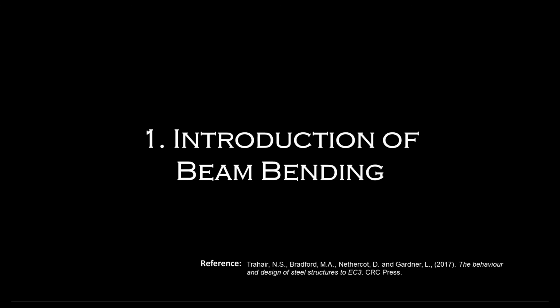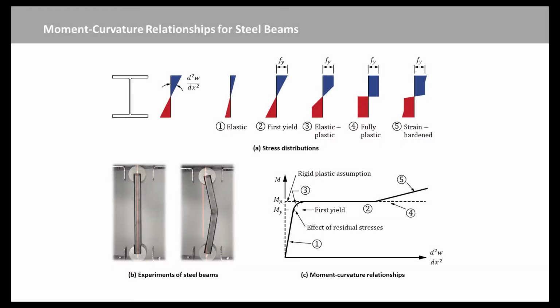Beams are structural members which transfer the transverse loads they carry to the supports by bending and shear actions. Beams generally develop higher stresses than axially loaded members with similar loads, while the bending deflections are much higher. These bending deflections of a beam are often, therefore, a primary design consideration. On the other hand, most beams have small shear deflections, and these are usually neglected.